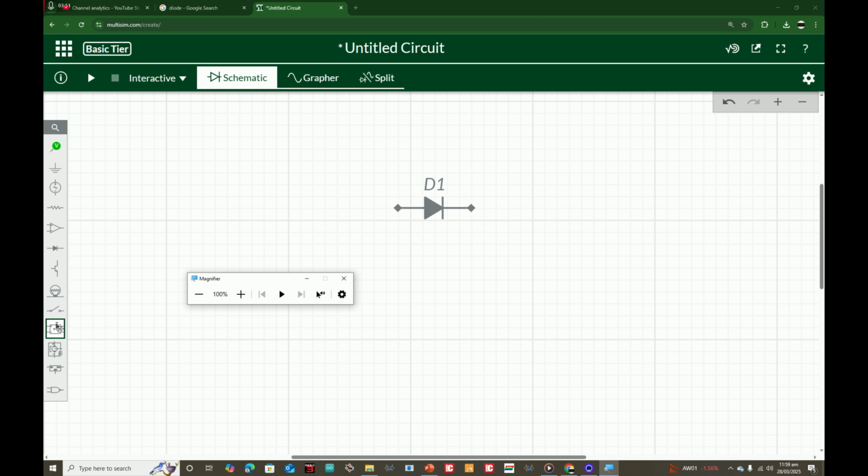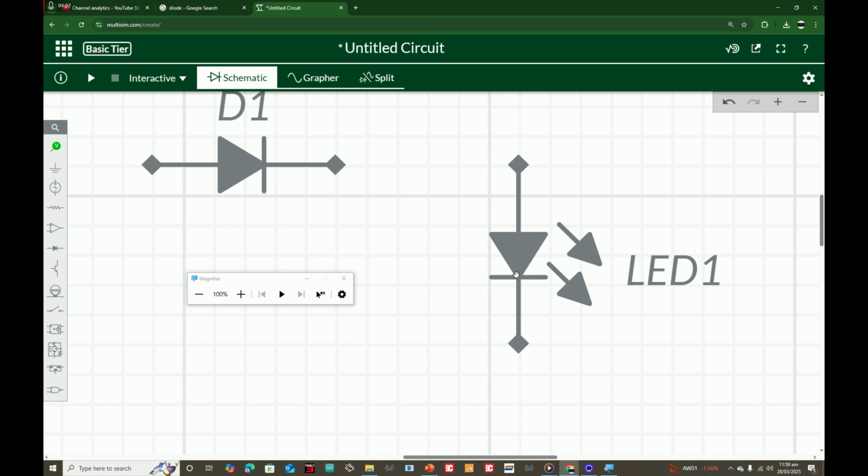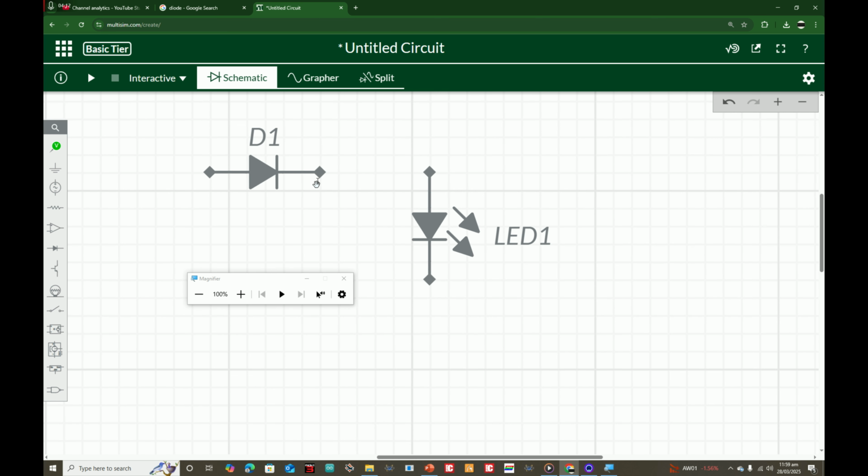Now guys, what we do is we make a small circuit. So we take an LED just like we did on the actual hardware. I take an LED like this. The LED itself is a diode. The positive should always be here. Now see why the LED has one pin longer and one pin shorter, because the LED, see the symbol, is also a diode. So if you connect it in the opposite direction, the LED does not glow, it gets burnt. Similarly, the diode only works in one direction.